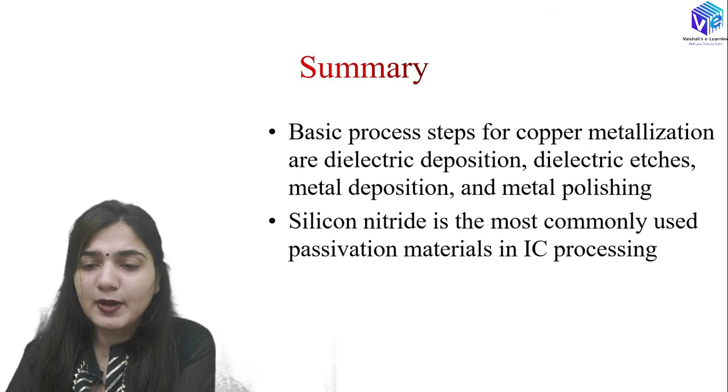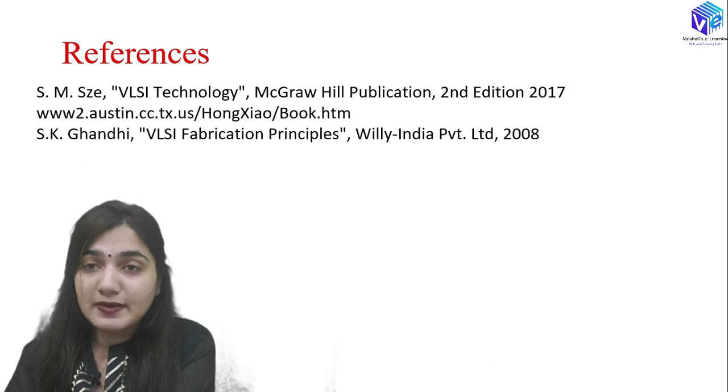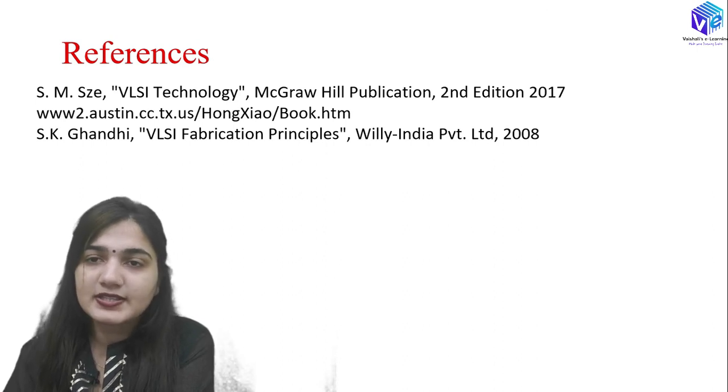After that we talked about the basic process steps for copper metallization and the dielectric deposition, dielectric etch, metal deposition and the metal polishing as well. After that we talked about the passivation. There I talked about the importance of silicon nitride and how it is the most commonly used passivation material in IC processing. So this is a very important book which you can refer for your further studies,